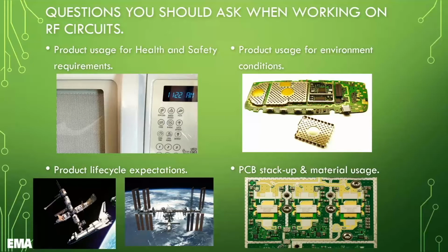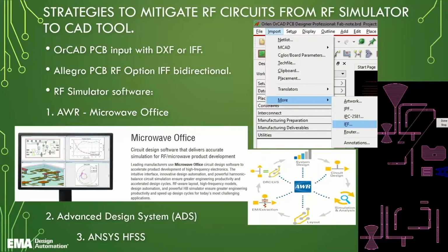So we need to look at the stack up. It's very important, the stack up. As you can see here, this board was framed off with different sections. There'll be a frame that snaps up over top of this and a metal shield. Materials used in that stack up are very important, because we do not want any of our signals necessarily oscillating out. So for material selection, plain FR4 is not really good for RF designs. With that said though, the key place to work is definitely with your board fabricator.